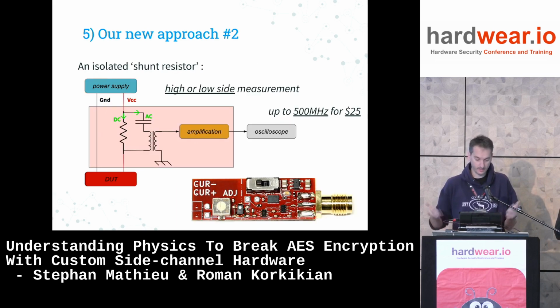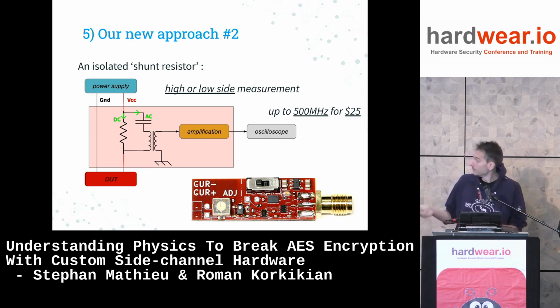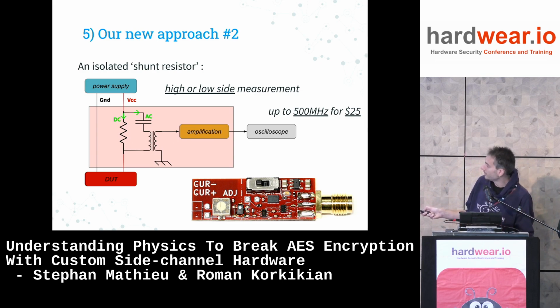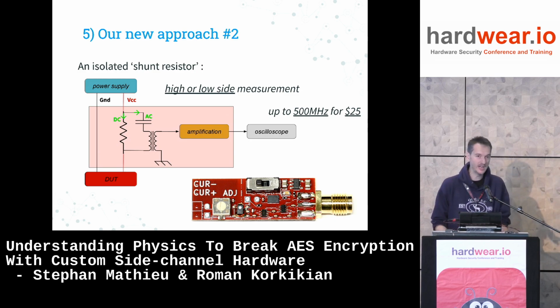Because I was on fire and I wanted to play, I made another board, which is a funky little device that allows low side and high side measurements. In short, you take that board, you see the two holes here. You connect it inline with the device you want to attack, because I realized that in some cases, when you have some fancy system on modules, it is not easy to just remove all the components and you just have a trace you want to cut and measure there. So this device was designed for that purpose.